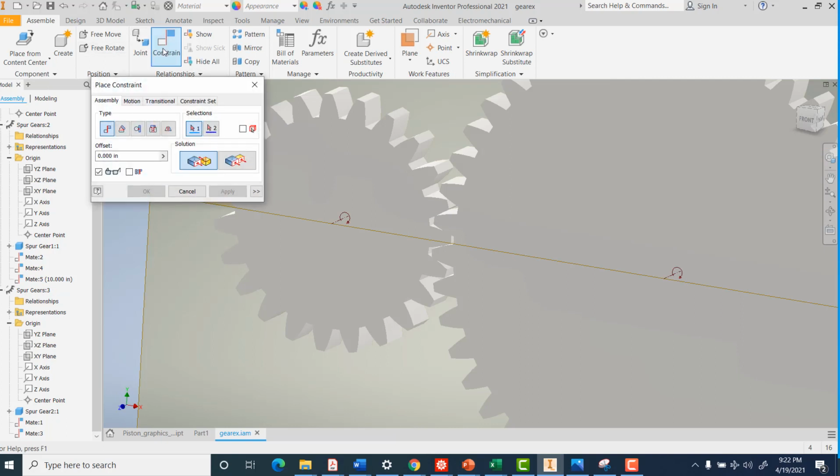Okay, now the really neat part, you can constrain their motion so they rotate with each other. So they go opposite directions. Make sure you get the opposite directions. The gear ratio, so we had that kind of weird 47 to 23. Notice I'm putting the large gear first, and I'm going to select the large gear first.